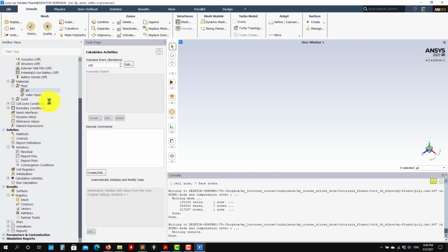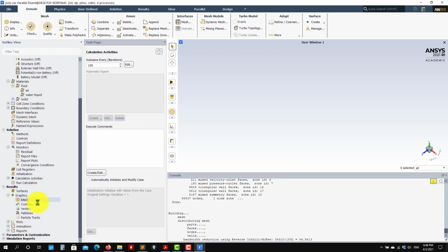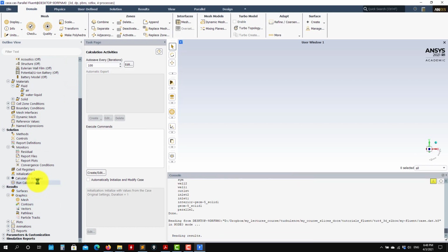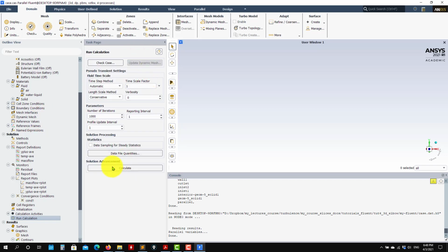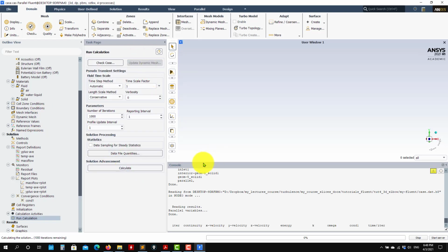But just to show you, let me go back to the tetra mesh, which is this case. And we have the whole setup. So we save everything, we're saving the whole setup. And at this point, we can run. Here, press calculate. So we're launching the tetra mesh here.